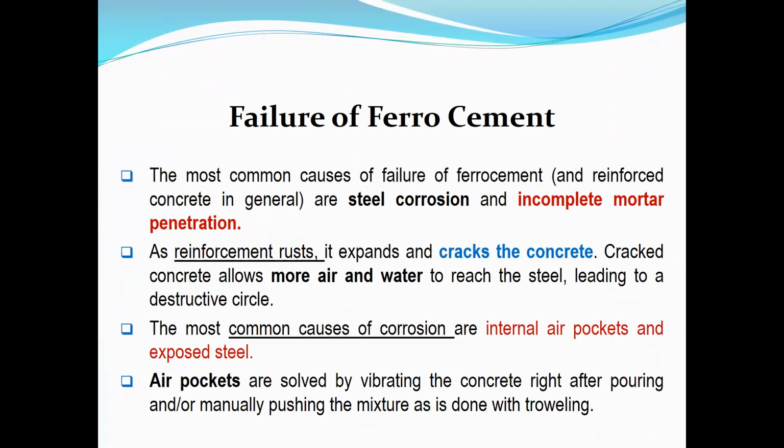This is very, very important for all types of exam. Failure of ferrocement. What is the failure mechanism of ferrocement structures? Very important. The most common causes of failure of ferrocement and also reinforced concrete are the corrosion in steel and incomplete mortar penetration. So corrosion is a common cause of failure for concrete, and this is also applicable for ferrocement structure. And another cause of failure is the incomplete mortar penetration.